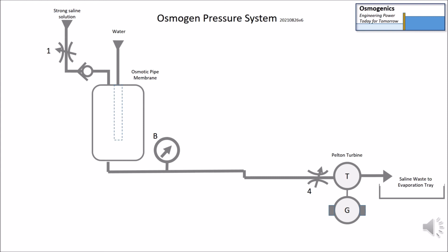Right, to make it a little bit practical, we put in a bladder, a pressure bladder vessel, so the high pressure brine then pressurizes this air, so we try and level these peaks of this water coming into the brine, and then we can control more finely the turbine, making sure it's operating at its optimum speed and flow. Now, this is just a one-cylinder engine. It can be equated to a one-cylinder engine, and we need more than one cylinder.